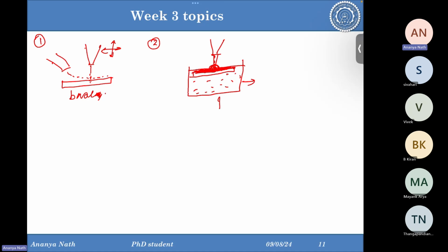When the first layer is done, this is the first layer, the build plate will lower down by one layer again. Now over the build plate there is one solidified layer and one liquid layer. This is the liquid layer and this is the solidified layer. And again the full resin vat is present and the laser is again coming from the top.